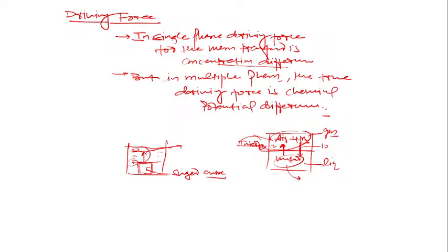It means that once equilibrium is established, the rate at which ammonia is transferred from the gas to the liquid is the same as the rate at which ammonia is transferred from the liquid to the gas. So there is no net change, no further change in the concentration of ammonia in the gas phase and liquid phase. As long as the concentration of ammonia in the gas and liquid phase is changing, the process is not in equilibrium.